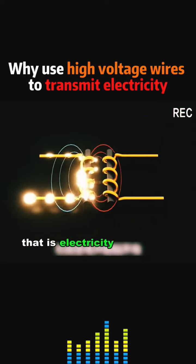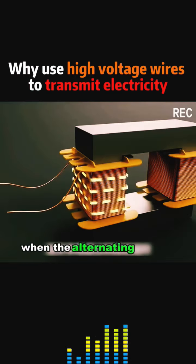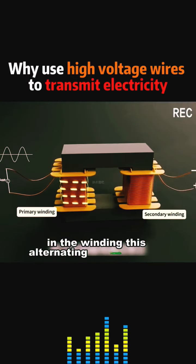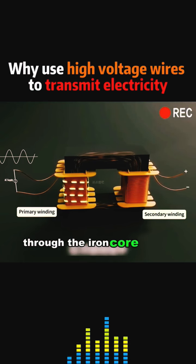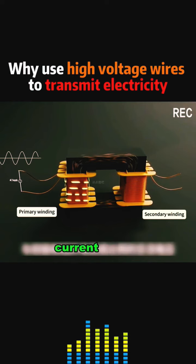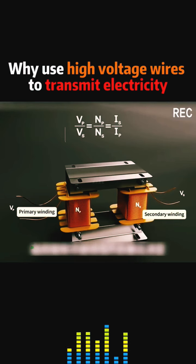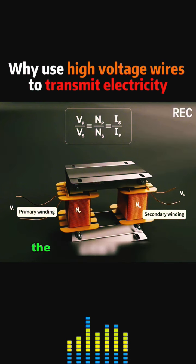That is, electricity generates magnetism. Magnetism generates electricity. When the alternating current passes through the primary winding, it produces an alternating magnetic field in the winding. This alternating magnetic field is transmitted to the secondary winding through the iron core. In the secondary winding, the alternating magnetic field induces an alternating current voltage proportional to the voltage in the primary winding. The voltage transformation relationship of a voltage transformer is determined by the turns ratio of the primary and secondary windings. The formula is as follows.